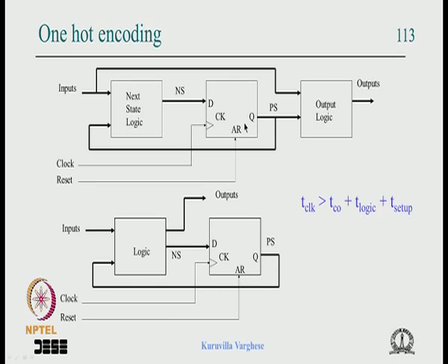We have analyzed the data path and tried to be very aggressive in its timing. But if you have designed a high performance data path and the state machine is slow, then nothing can work. So it is not a good solution.